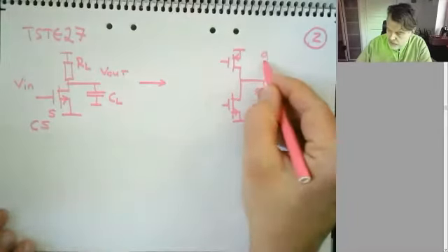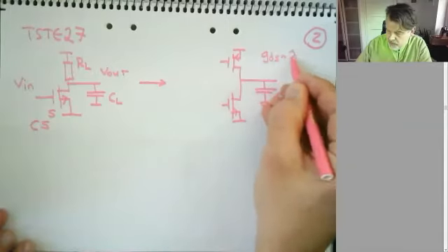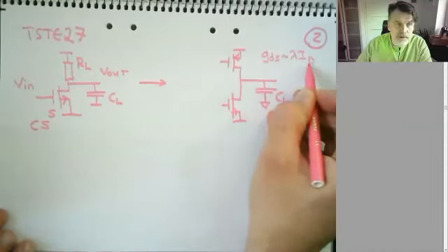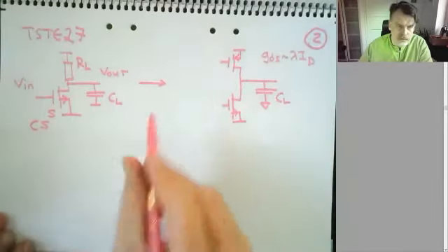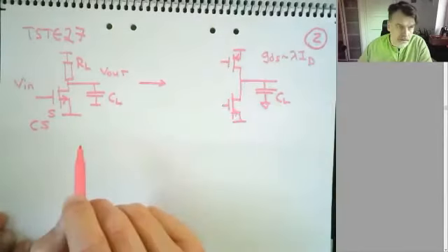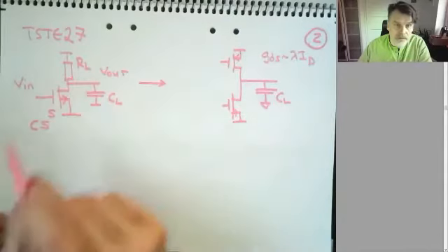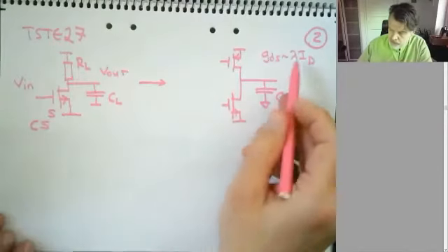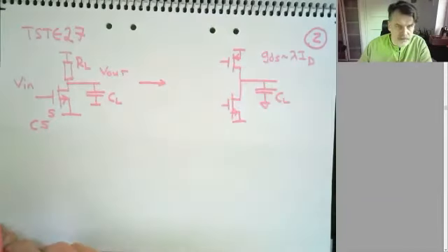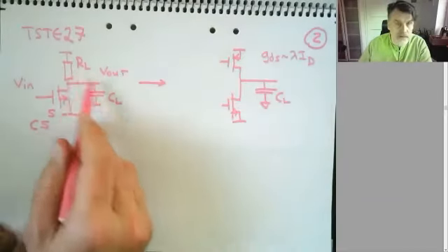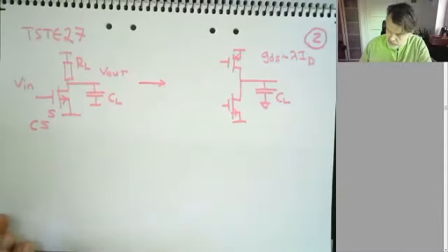It's not really true because we have GDS equals lambda ID, so it's definitely dependent on the current, but it's a value which is, for its physical size, much larger than what it is for a resistor. And the current that I can deliver to the output is sort of inherently given by the transistor itself, rather than here where you have a sort of RC dependency.